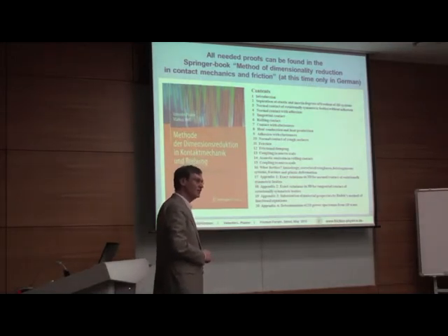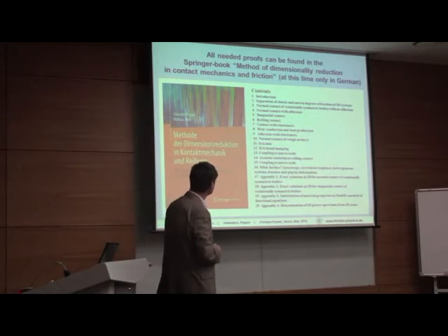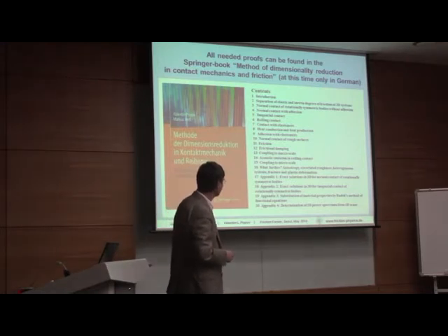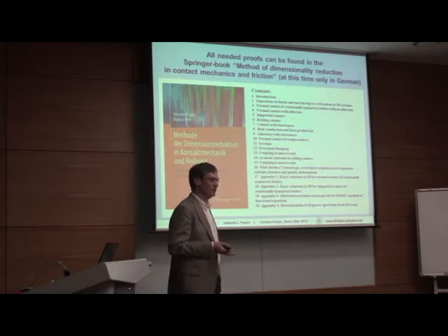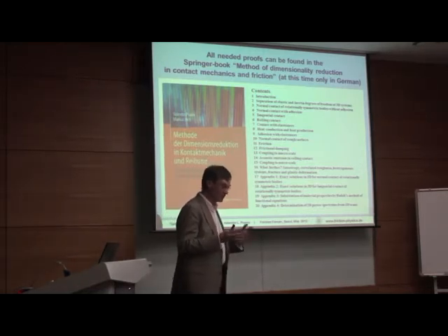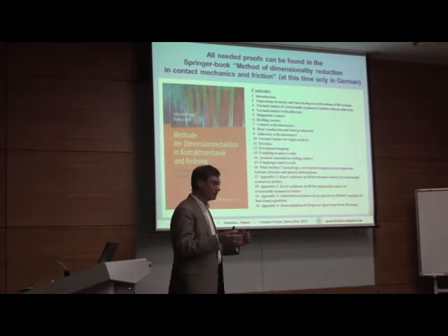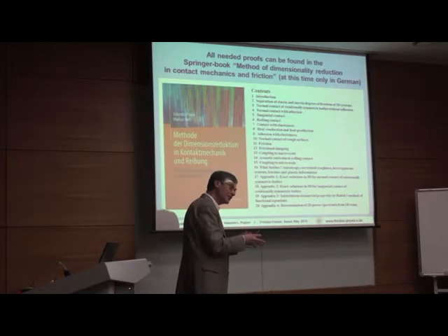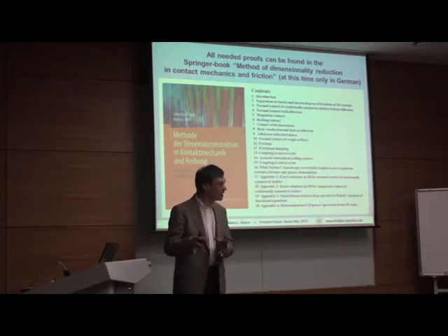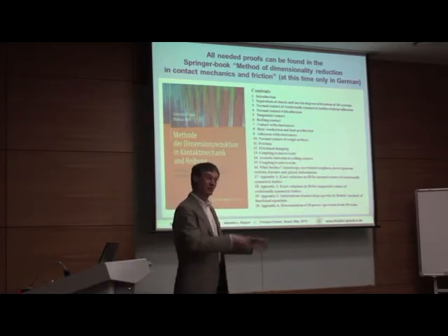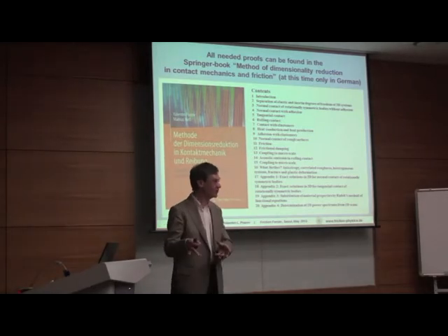For number 19, you substitute some material properties by Radok's method? The viscoelastic is based on Radok. Yes. Okay, because Radok's method is in principle a statement that if you have an elastic solution, then you get the viscoelastic. And we have the elastic, and we show how to get viscoelastic.